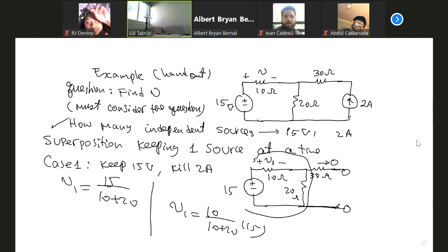You tell me that this is a circuit, the current goes here 0. It's a single loop circuit. And somebody says, I cannot measure the current. The other person says, this is 15 volt across V1. Why? I mean, this is a loop. Another person says, there is a current going on here. As soon as I ask you what's the current, at least I should hear, okay, voltage divided by summation of 2 resistors, or voltage division law.